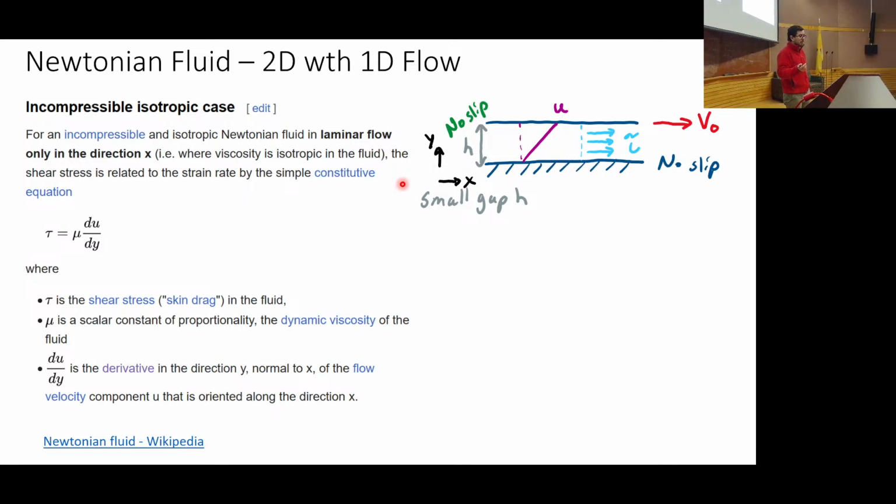About 1 millipascal second, and a lot of the oils start at the viscosity of water and move up. How do the oils change their viscosity? What is the viscosity of an oil dependent on? It's dependent on chemical composition, but there's one other thing it's usually dependent on. Any idea? Temperature? Okay, temperature, yes. Temperature makes a big difference.